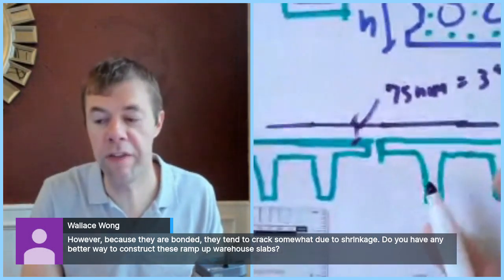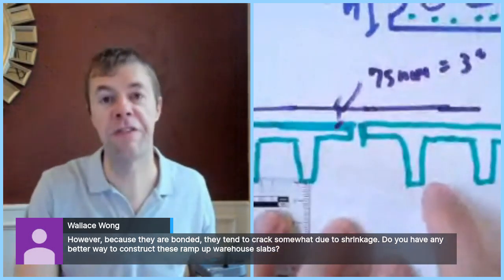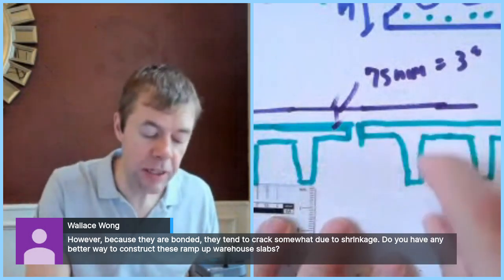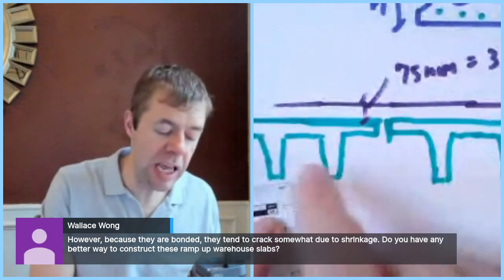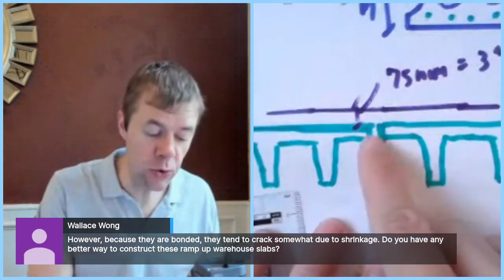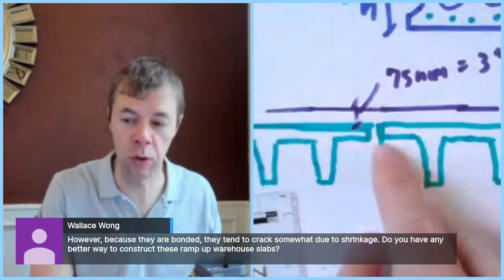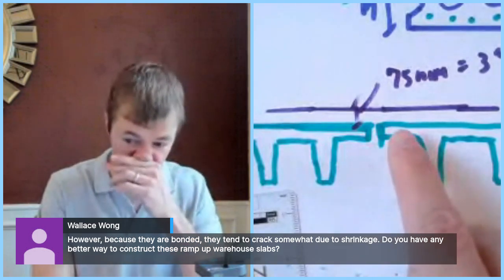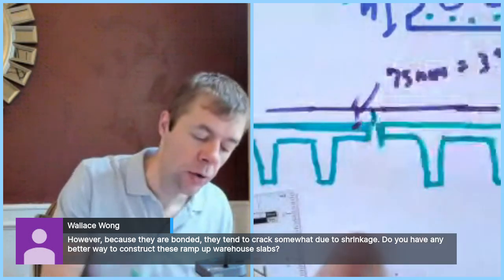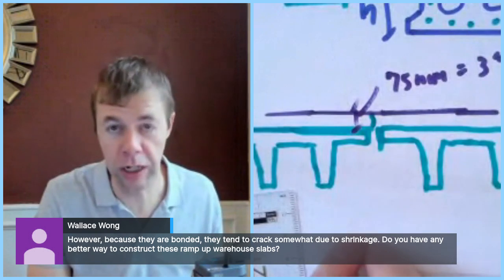So first of all, if you're in a warehouse, oftentimes these systems you're hooking to are not very stiff. That means they're going to move a lot. That means they may even move a lot differentially to one another. And if they do, then that is going to work that slab a lot, especially the joint in between where these two places are. It's going to work it a whole lot, and it will likely cause a crack to happen right there. And some kind of reinforcement across it is about all that you can ever hope to do.